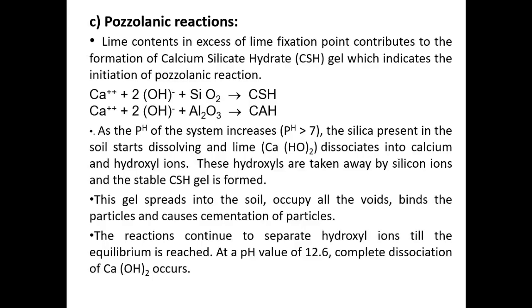Next one is pozzolanic reactions. The reaction between the silica present in the soil and calcium in the lime along with water to produce cementitious compounds is a pozzolanic reaction. Hydration is a quick reaction, whereas pozzolanic reactions may continue for many years as they depend on the moisture and temperature conditions.